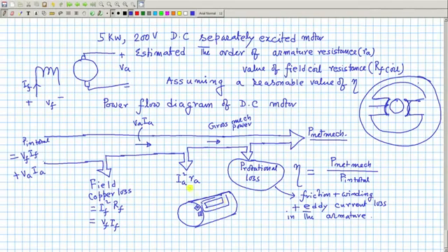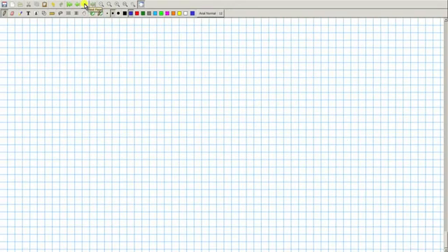That is why, for the rotor or the armature of a DC machine, you cannot use solid iron. You have to use stampings, okay? Circular stampings. In this case, for example, it will be like this.